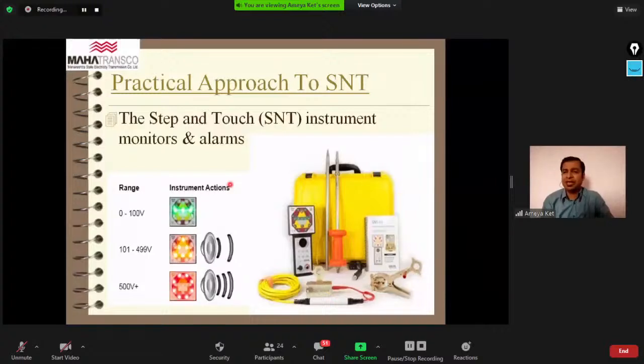We are maintaining the earthing, watering, and yearly we are taking earthing values and making corrective action. So we are very much aware that our substation earthing is in proper shape, and we are able to work with good confidence on that earthing area. But while working on transmission tower lines, tower line earthing maintenance is not as feasible, possible, and easy as it is in the case of EHV substations.